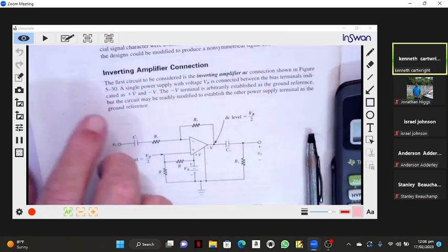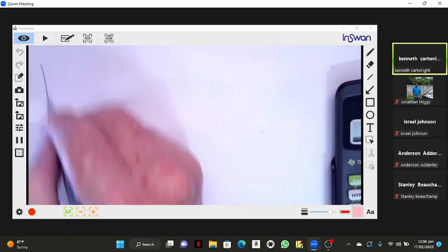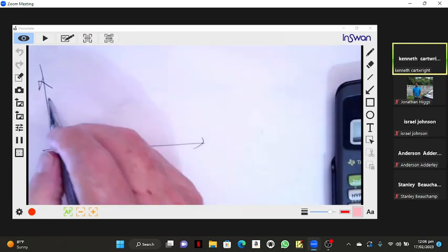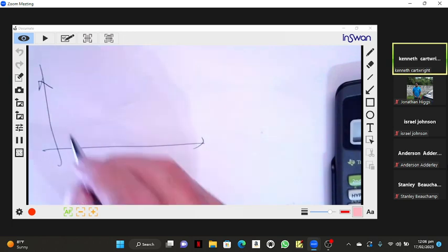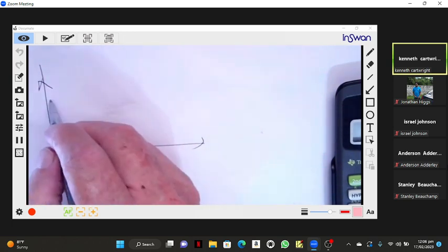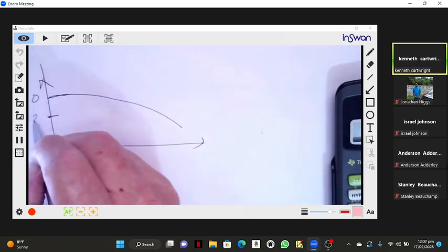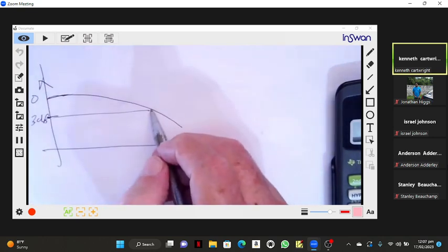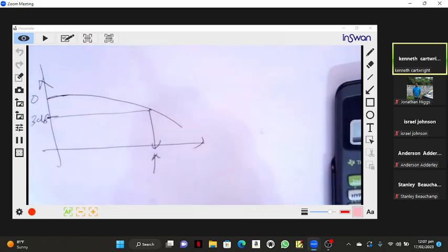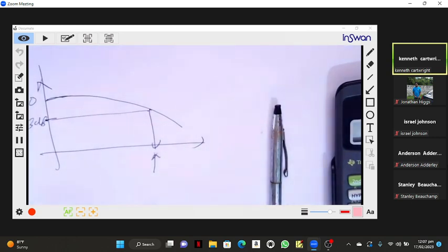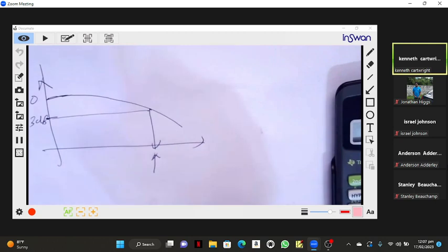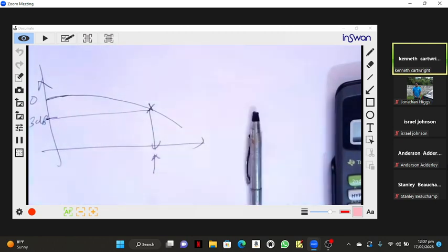Let me go back to that statement I just made. What I asked for was this. If you did the Bode magnitude plot, and you did it far enough away, you'd have found out that it drops to -3 dB. And I asked for this frequency here. That's the highest frequency I asked for. You could have gone over that, but you would have had to select that point and let me know that it is the -3 dB frequency. Only a few people did this.